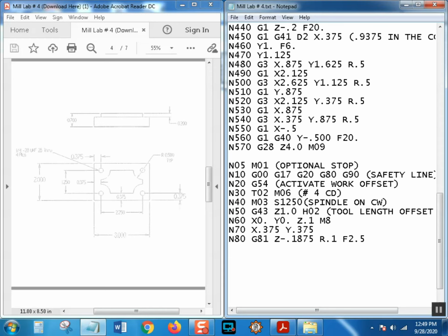Trust me, on 90% of the jobs you do, unless you're working with some weirdo metal like Hastelloy, Alloy, Inconel, or maybe 400 series stainless, that feed will work real well for most situations. And remember, you have a feed rate override control on the CNC control anyway, so you can change the feed rate if you like anytime.